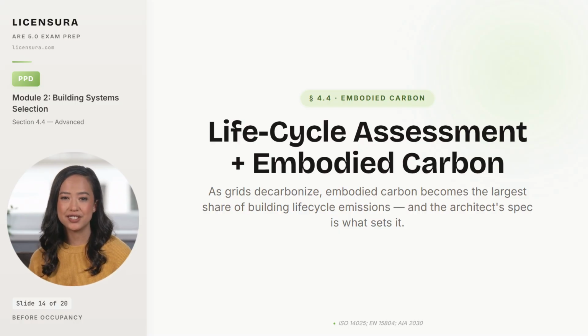Life cycle assessment, abbreviated LCA, is the standardized methodology that quantifies environmental impacts across the entire life of the building: material extraction, manufacturing, construction, operation, and end of life. The LEED rating system awards credits for whole building LCA, showing a 10% reduction in at least 3 impact categories.